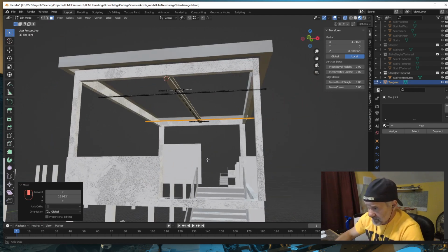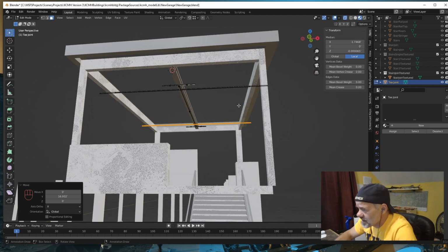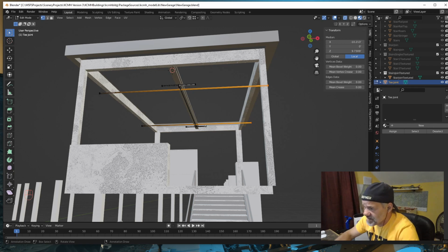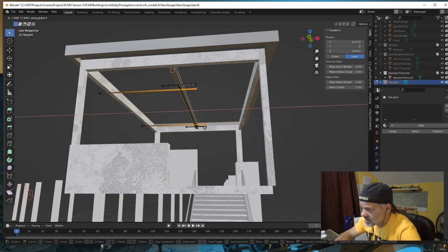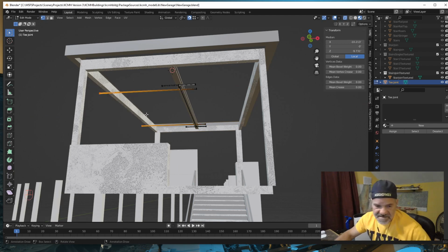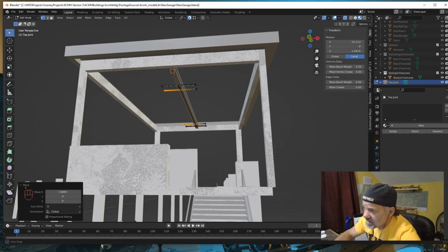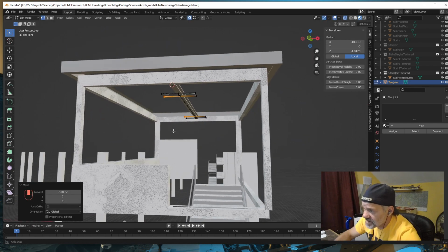Unless you suffer from OCD, sorry. All right, now I want to take these vertices and move those even with these over here. So turn my snap back on. GX, snap, and then select these vertices, GX, snap. So that should look something like that.